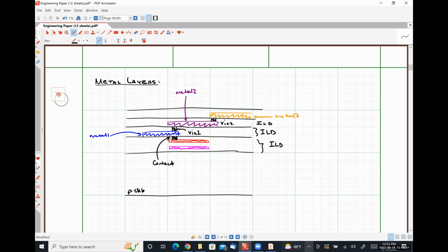Why might this be a bad idea? You only have one, then wouldn't that mean if you want to get to the lower levels, you'd have to use that one connection all the way down, bypass the intermediate layer? So you can't use it to bypass the intermediate layers. The problem with only using a single point of connection is that if it fails, you no longer have access to those other regions of the chip.